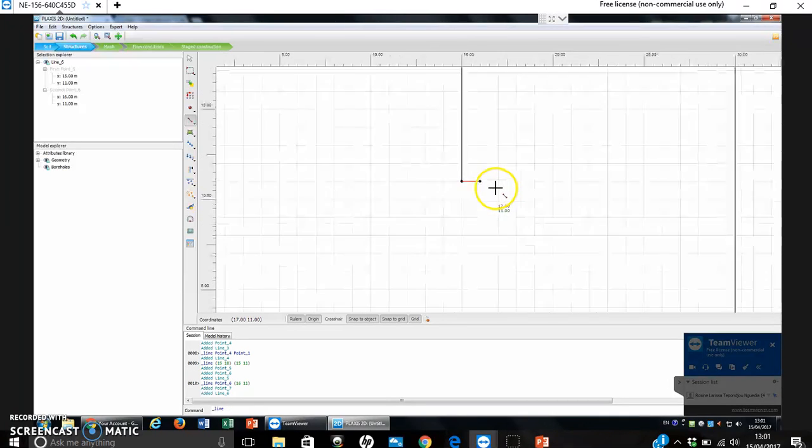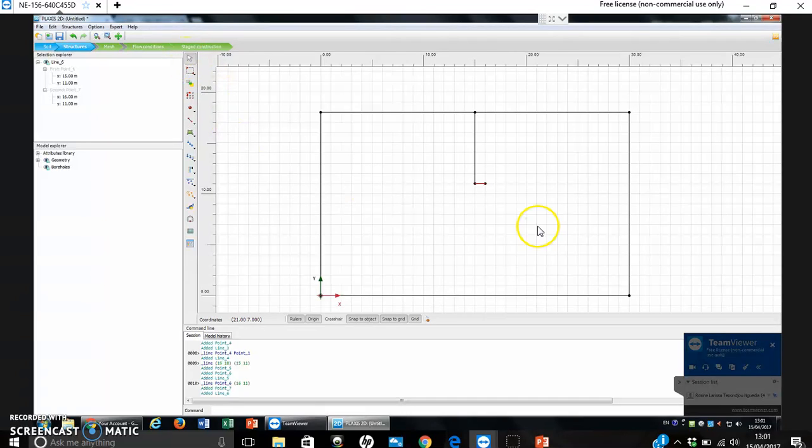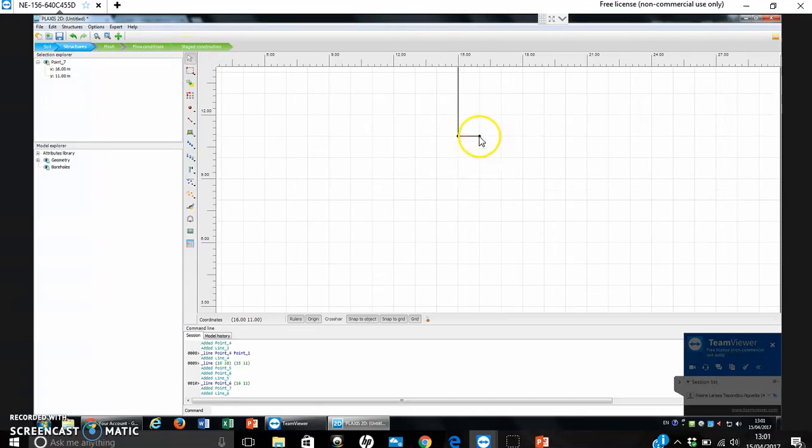Right click. If I come out using that arrow, click on this last point here, it gives you the dimensions. So we are at 11 and that is 16, so we want it to be this point here is 15, 11, and here is 16. So from 15 to there is 0.4. So we're going to change it to 15. Oops, no, leave that at 15 because it's going to change that point. So click on that point and put here 15.4. There you go. It changed the dimension automatically for you.